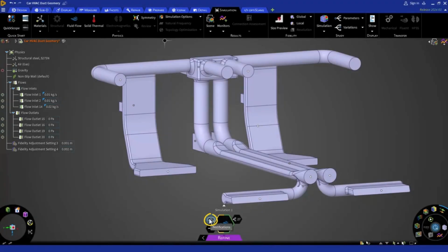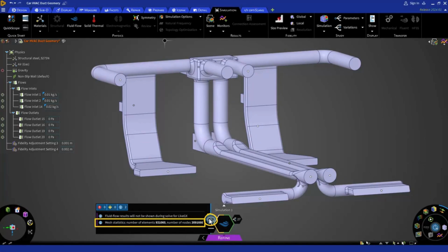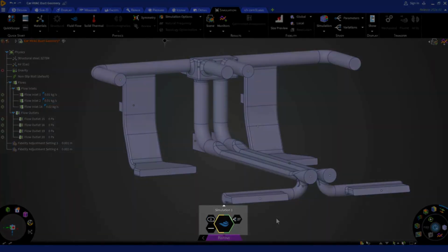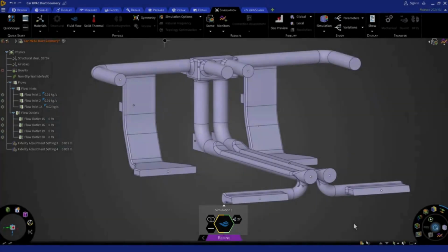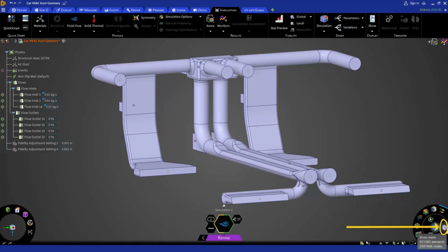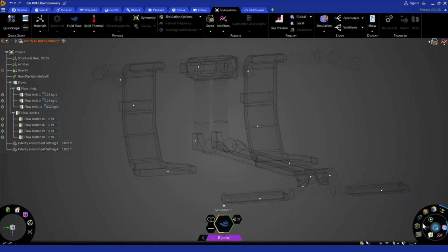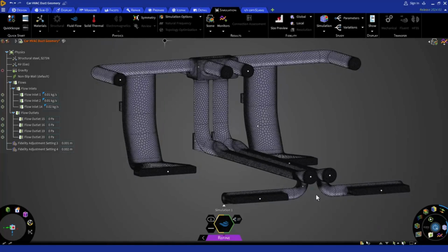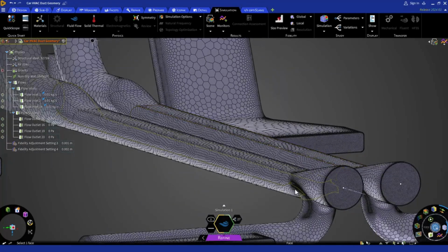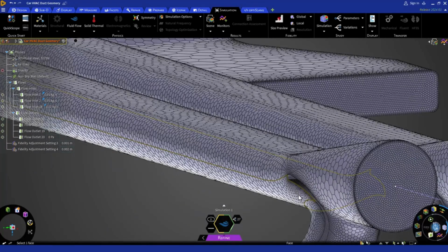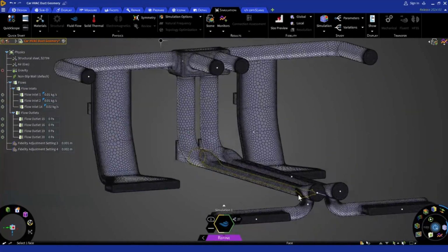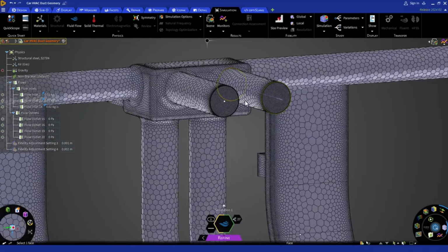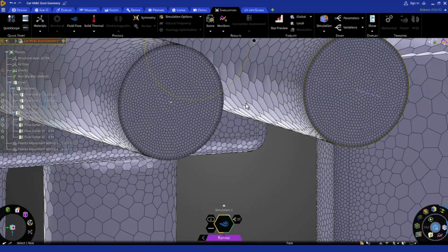You can see the mesh statistics when they are available by going to the notification section. The meshing task is completed when the green revolving line reaches the half mark on the simulation information display or SID. To see the generated mesh, click on the same mesh icon next to the solve button once your meshing is done. Let it run for now and then we will talk about some results here in refine mode and how much difference we are seeing from the explore mode.